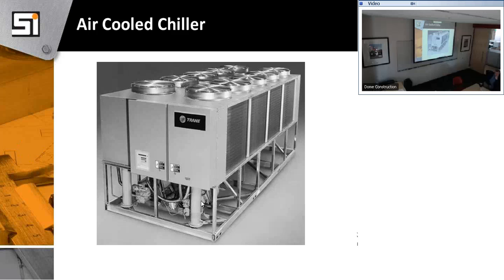Like Genentech, they're trying to go more campus-wide right now. They're trying to create a campus chilled water system. Stanford does it, but it's bigger places. If you've got a maintenance department, it makes sense to go water cooled. But if you don't have a maintenance department maintaining that water cooled system, it can be in deep trouble. We only have a couple more minutes.